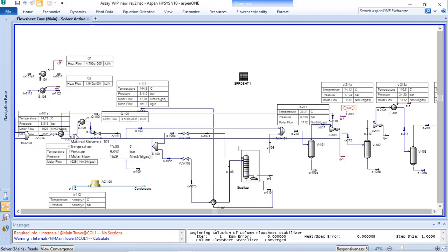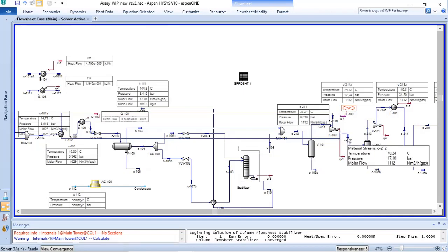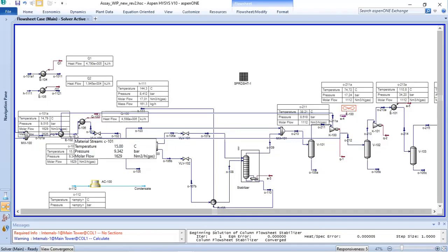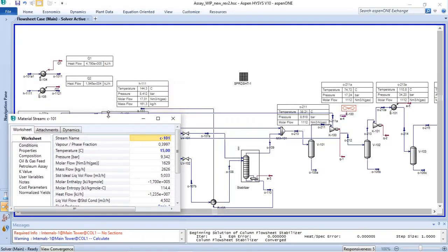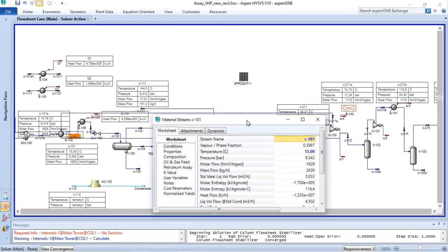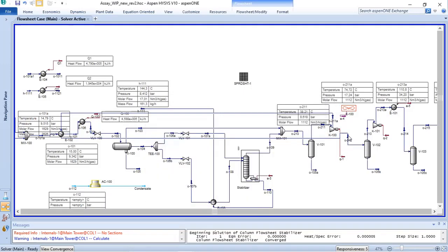And now let's see the outlet of the compressor going out as 74 Celsius and returning with 70, so I have some space for heat exchanging. Let's verify now if it's possible to remove the electrical heater, increasing the outlet temperature of the preheater. And to follow that, let's see the return temperature.